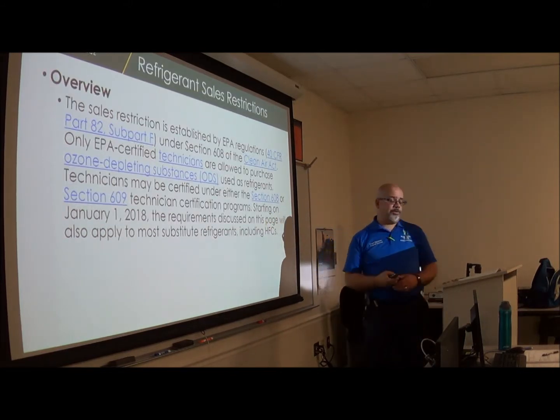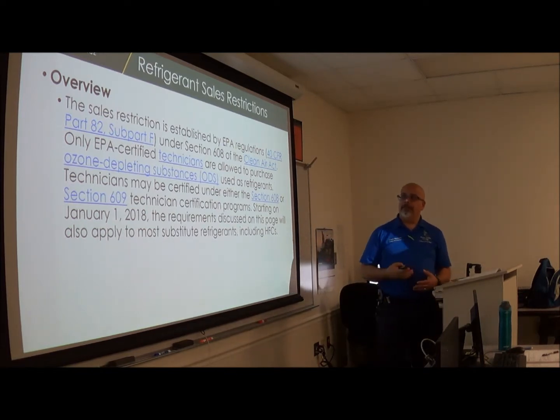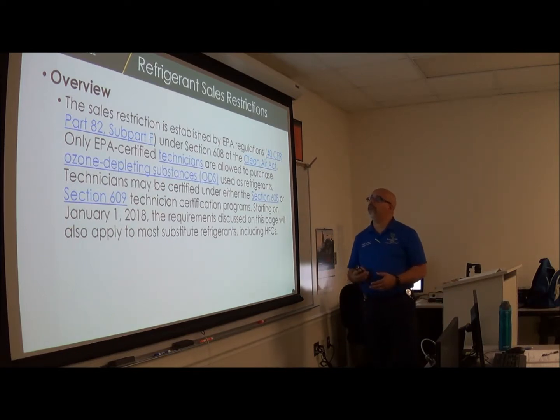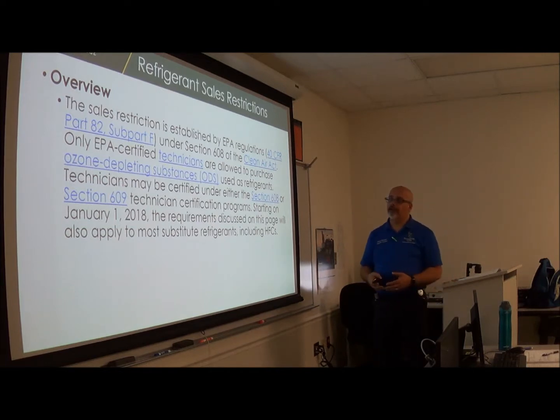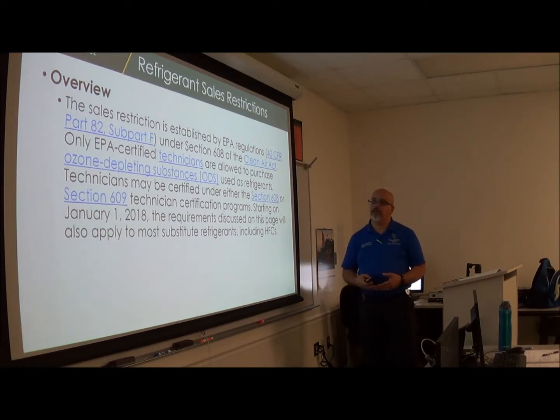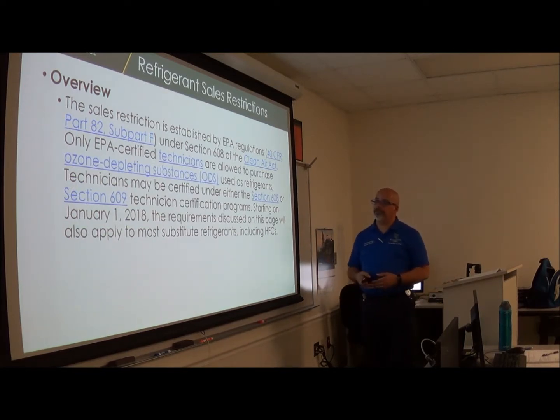Refrigerant sales restrictions. There is an overview on this. The sales restriction is established by EPA regulations 40 CFR Part 82 Subpart F under Section 608 of the Clean Air Act. Only EPA certified technicians, which is why you're taking this training today, are allowed to purchase ozone-depleting substances used as refrigerants.